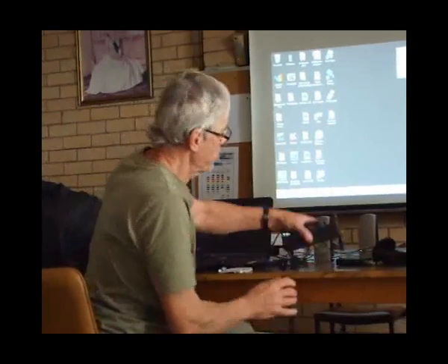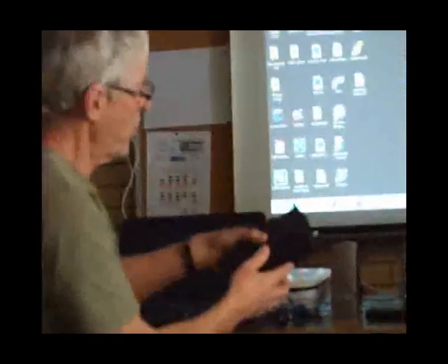Everything's done in software, and I've also installed a narrow crystal filter to minimise the effect of close-in stations, which can overload and destroy your sensitivity. Inside, there are these little fold-down feet, and you just undo these little screws here. The radio comes apart like that.